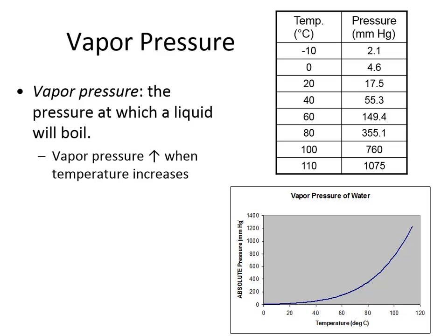It requires a lot of energy to do. But if I heat the sap up to 80 Celsius, it's not going to evaporate very quickly because its vapor pressure isn't high. It's worth it to me to get it up to 100 Celsius because by just increasing it 20 Celsius, I get a much higher vapor pressure, and it'll evaporate a lot faster.